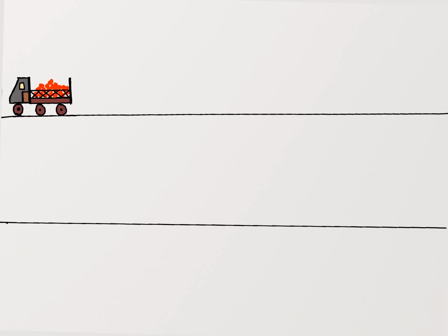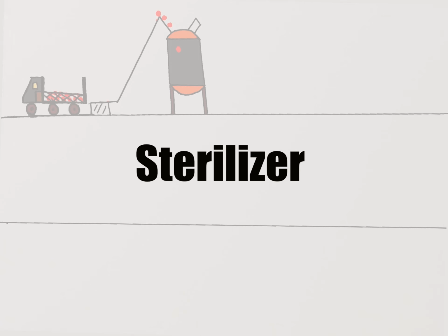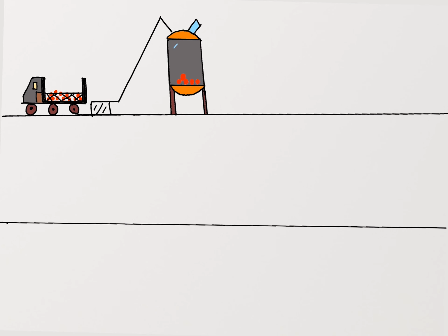The fresh fruit bunches (FFB) is transferred into the sterilizer using a conveyor belt and steam is added to cook the bunches in a cylindrical pressure vessel for about 60 to 90 minutes. The heat will stop the increase of free fatty acid and weaken the fruit stem for mechanical stripping. The sterilized FFB is sent for stripping process.